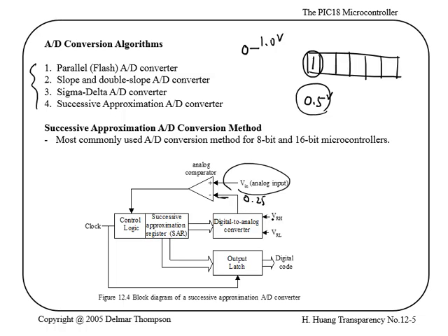If it is less than, then you would put a 0 here, and so on and so forth. You go until you have 1 over 1024 volts, if you have 10 bits, and that's going to determine if you have a 1 or 0 here, and that's going to take the value.